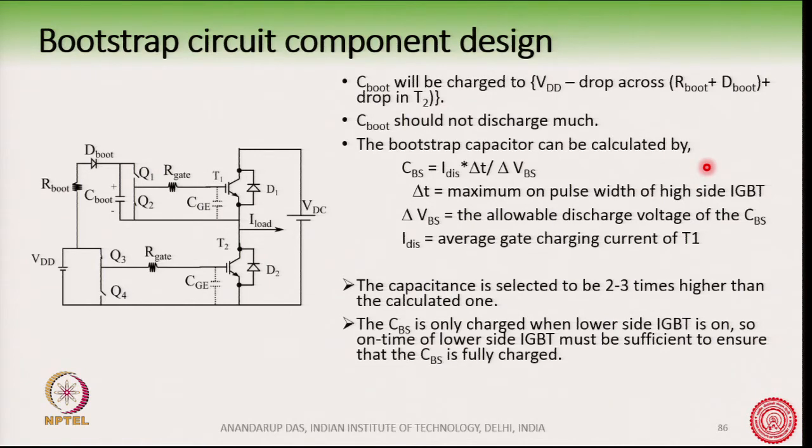So, this bootstrap capacitor can be calculated. C bootstrap, the value C boot, is equal to I discharge times delta T divided by delta V bootstrap. How long will it discharge?